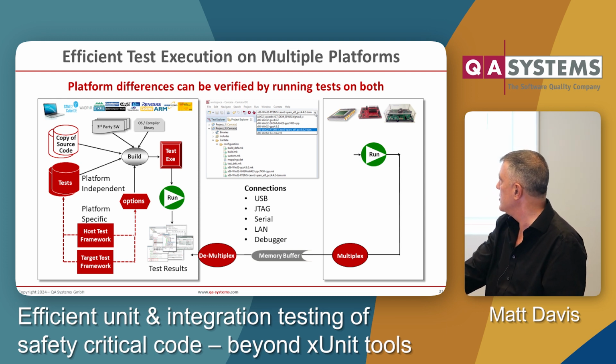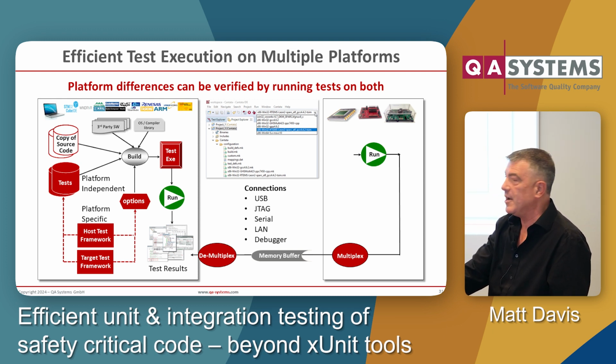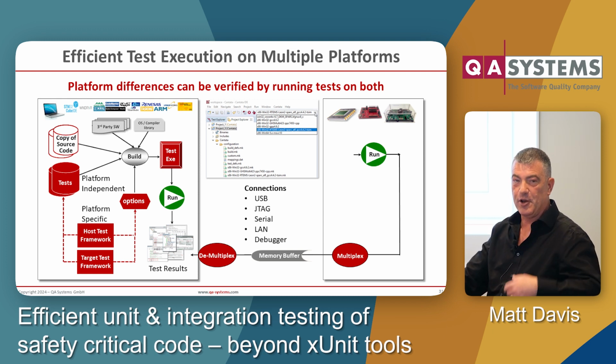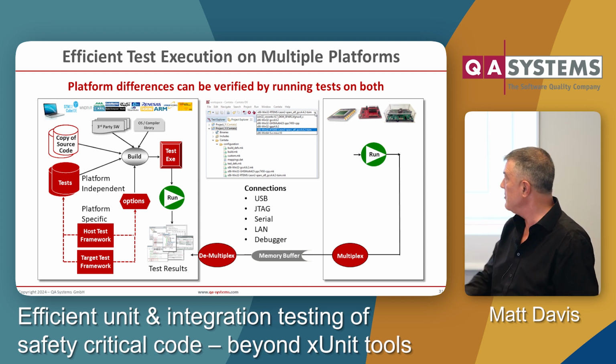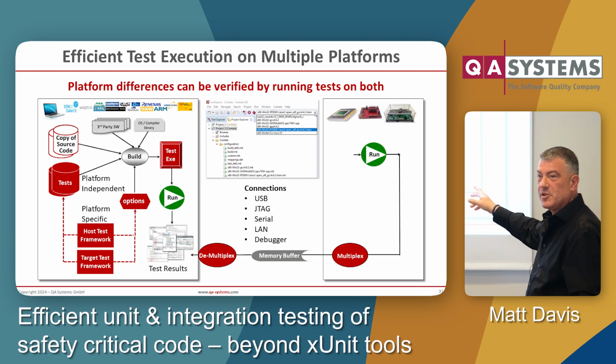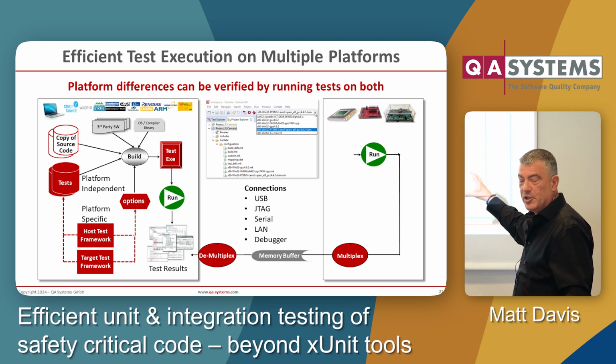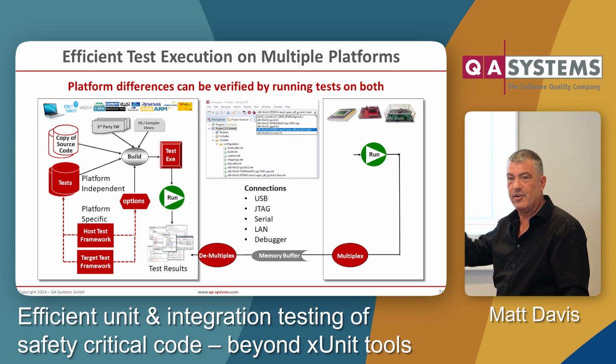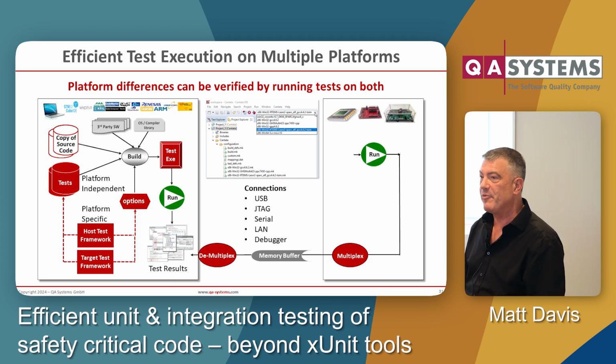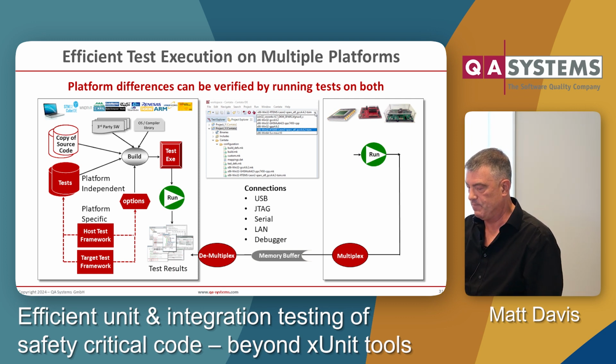When it's run on the target, you get output. Now, not everybody has super file I/O on a big fat RTOS. Most people don't. I'd say about 90% of our customer base don't. So we use an automatic multiplexer and demultiplexer to take character streams or flash memory buffers or whatever from target to host.